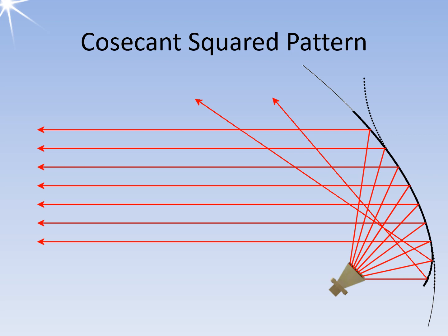The reflector can be fed using a horn radiator as a point-like source, which results in a double curved shape of the reflector. Alternatively, it can be fed from a linear slotted waveguide array, which results in a single curved reflector known as a cylindrical parabolic reflector.